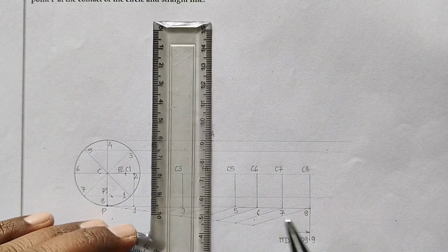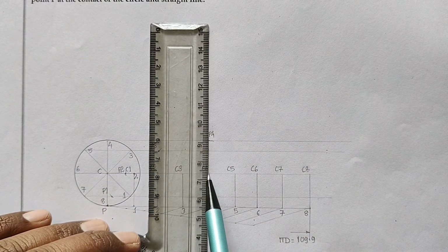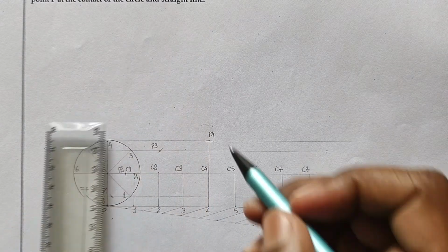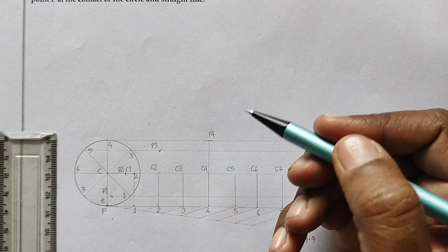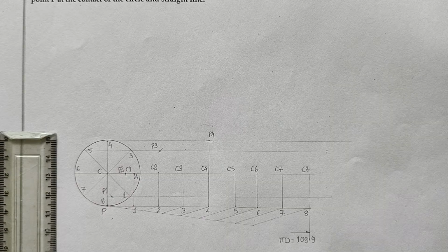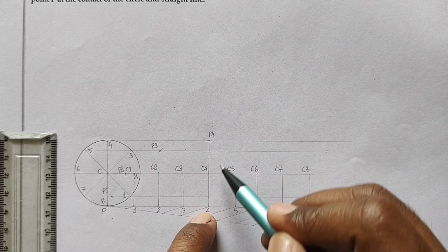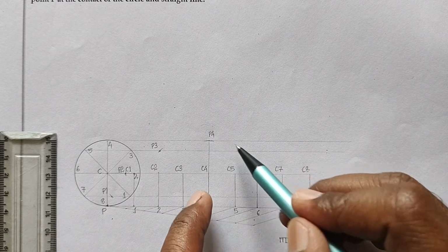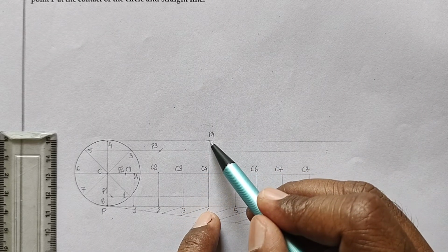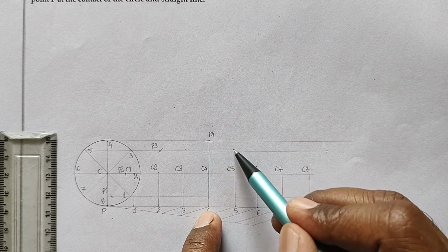Else you can do one thing, you can extend this center line C4 and exactly match to P4. Now once the P position is here at 4 division rotation, hereafter when it rolls through the 5th division, the P point will now slightly move down.